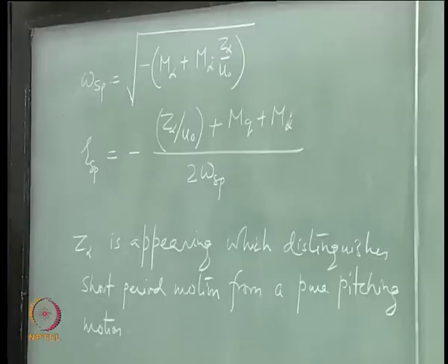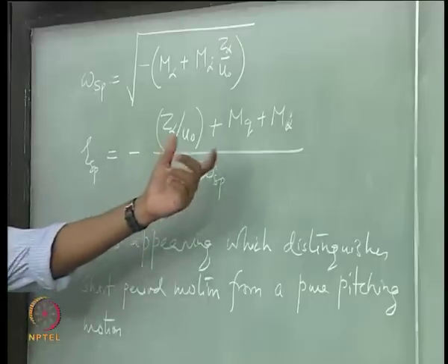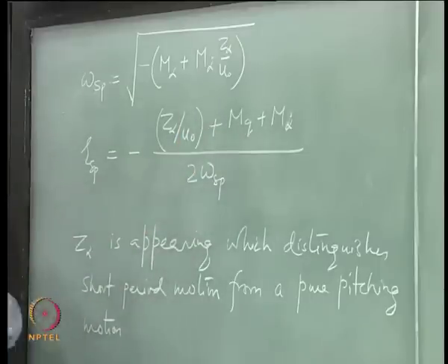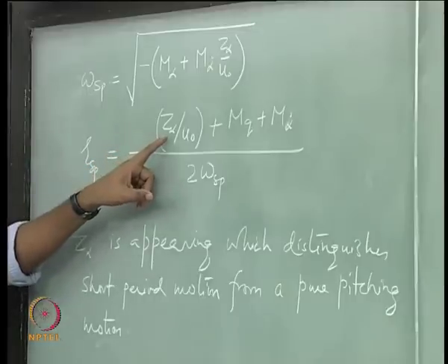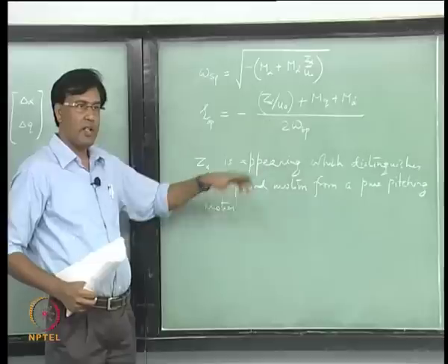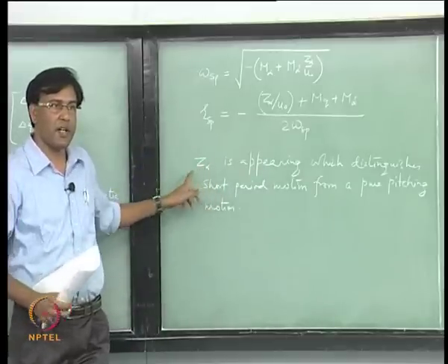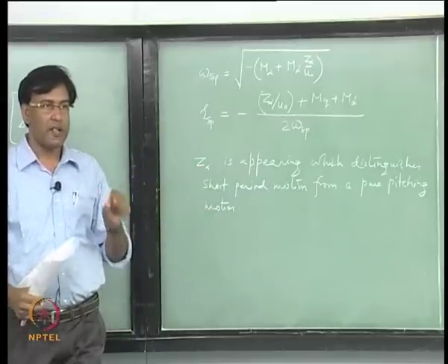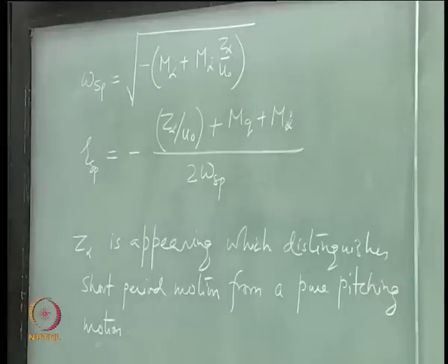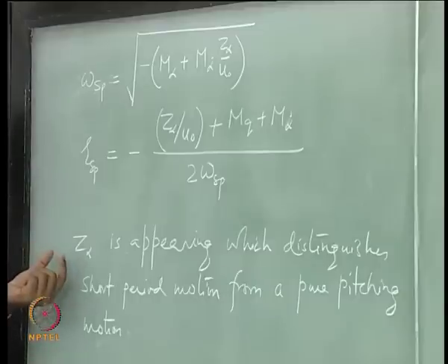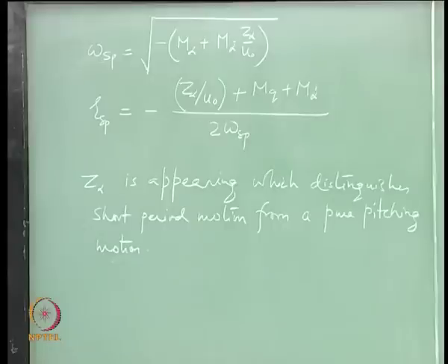So even after this short period mode is damped out in pitching motion, because of this particular term, which is like vertical motion with respect to change in angle of attack, a residual remains, and there are people arguing that this will probably result in an ensuing phugoid motion, right.